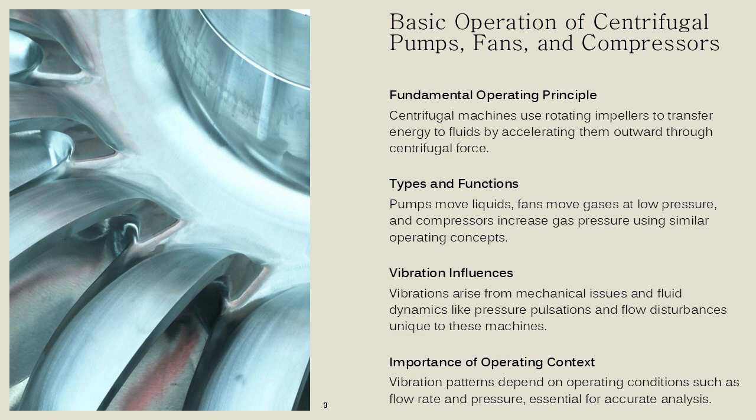Therefore, vibration analysis of centrifugal machines must always be interpreted in the context of how the machine is operating at the time of measurement. This foundational understanding sets the stage for identifying specific vibration sources such as blade pass frequency,